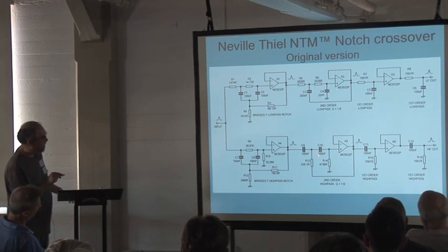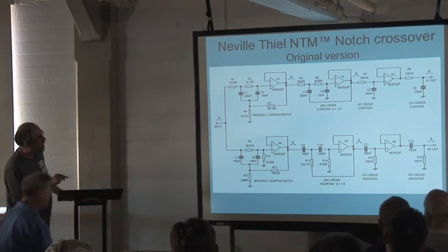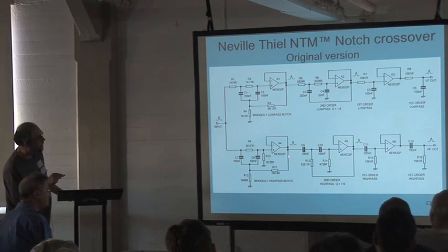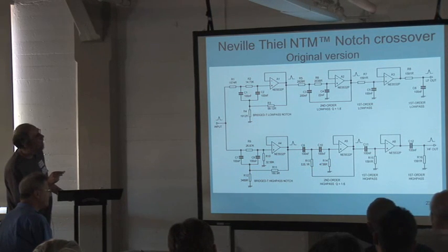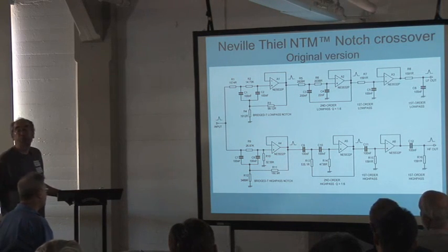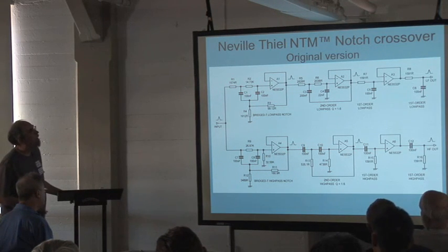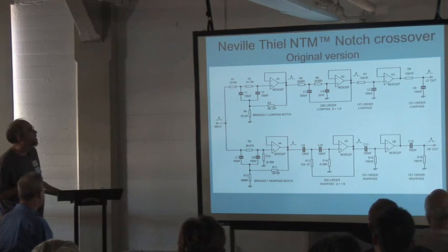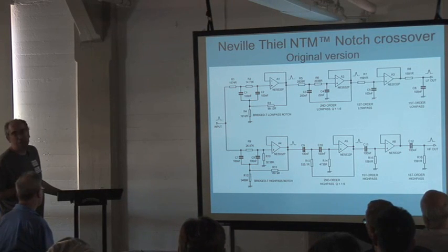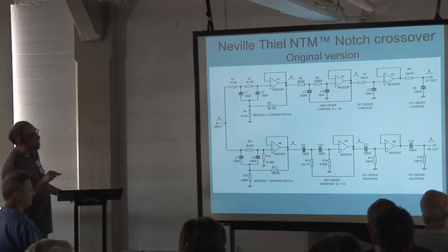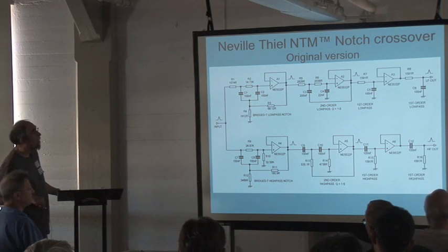After that, you've got the second order filter, once again peaking, and the peaking being arranged by the ratio of these two resistors here, which is, as you can see, quite a hefty ratio. And likewise with these capacitors, you've got 200 nanofarads there and 22 there, which is not the sort of thing you very often see in a Sallen-Key filter. A Q of 1.6 is probably about as far as you want to push that configuration. You'd have to use something more sophisticated if you wanted a higher Q. Right, then the first order high pass and the second first order high pass, once again buffered from each other so you get the correct response.